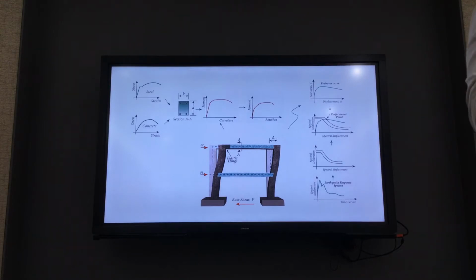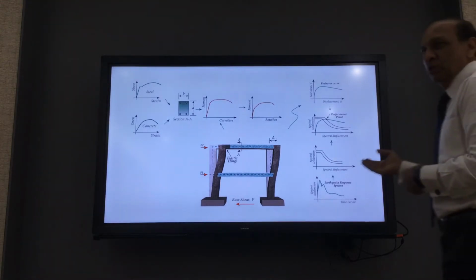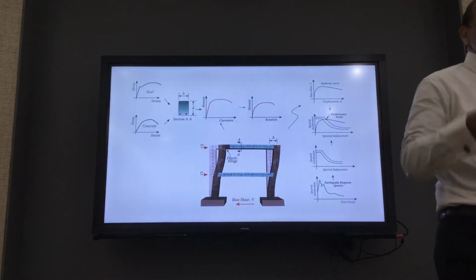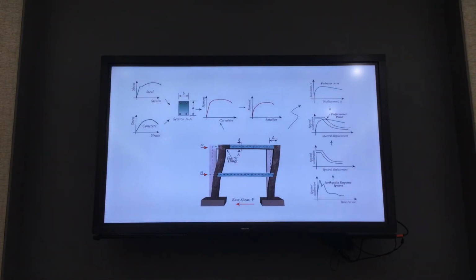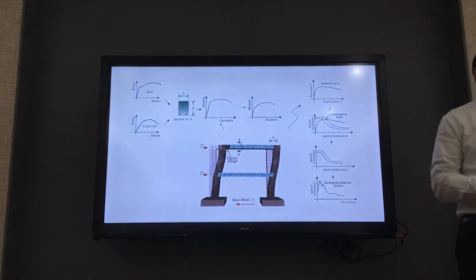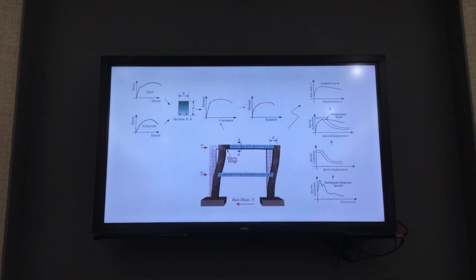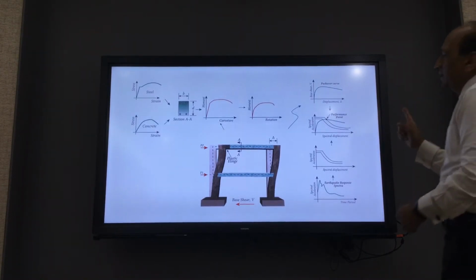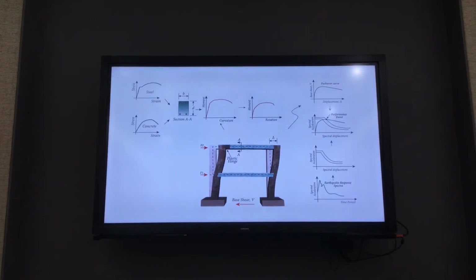Multi-mode pushover method and adaptive mesh pushover method and this pushover, all kinds of methods, right? Just like confinement curves. So many confinement curves, confinement models. Same thing with the pushover. So many pushover methods came into being. And then it became popular, and then slowly they died off. And now 2 or 3 remain that we still use. One is called multi-mode, and we sometimes use it. And even this can be used for single mode pushover for small structures and for understanding the behavior of the structure. So that is the starting point of the performance-based design pushover